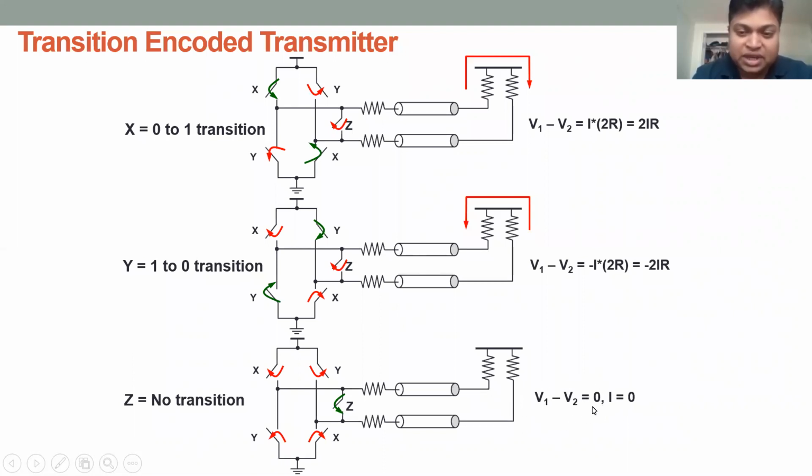So one might ask, if there is no differential voltage, why do we even need to turn it on? Because there would still be some ringing that needs to settle down, and that's why we need this termination on this side, to avoid the bounce back and forth of the reflected signal. So that's why we still have to terminate it, right? And at that point, there is no differential voltage. We would have the receiver's common mode, the way we have it, right?